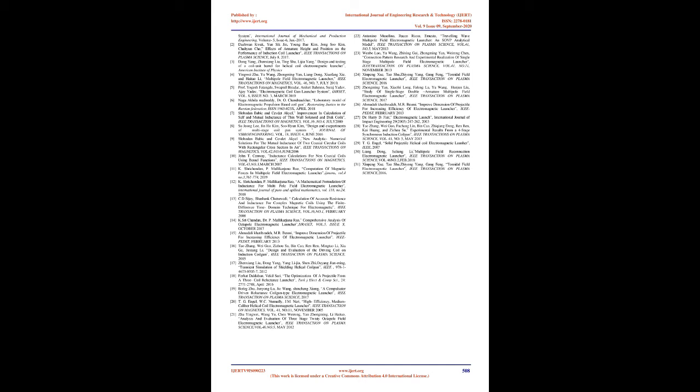4. Reluctance coil gun launcher. It uses attractive ferromagnetic properties to accelerate the projectile. The coil is magnetized by carefully timing the coil current, and the attractive forces of the coils pull the projectile upwards sequentially. Its energy conversion efficiency is higher than the induction coil gun because electrical energy conversion only takes place at the excitation coil, so there is negligible eddy current in the projectile. Timing the current pulse is a crucial parameter of this launcher, otherwise it can experience the suckback effect.